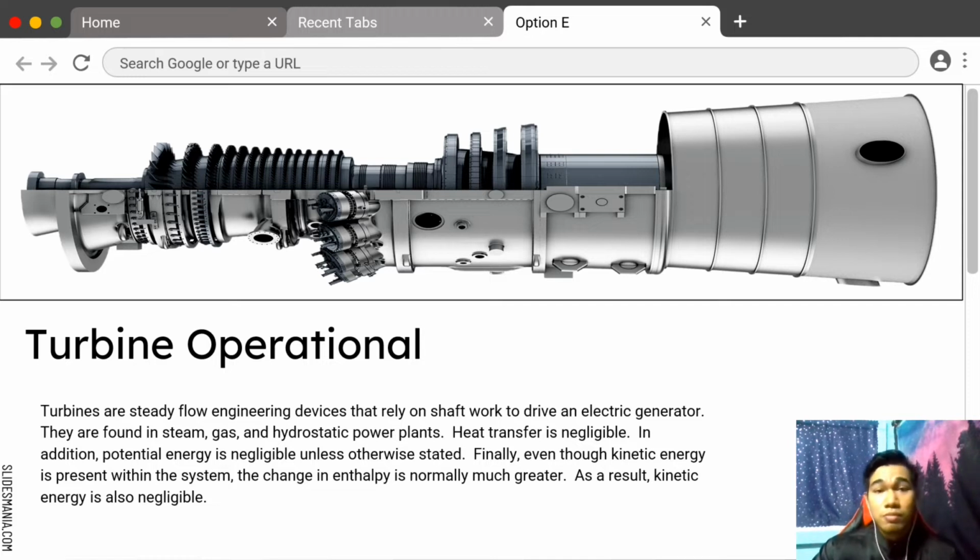During operation, superheated steam will be pushed through the turbine. As this is occurring, it is possible that the steam could become a saturated gas when it leaves. This must be taken into consideration when you are calculating the exit enthalpy. Finally, liquid can damage the blades of the turbine. As a result, it is best to keep the fluid in a gas state as it passes through the turbine.